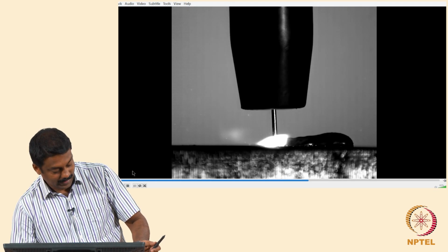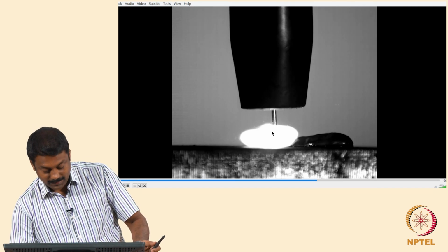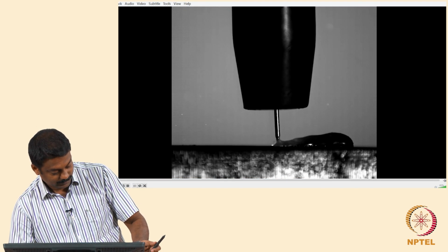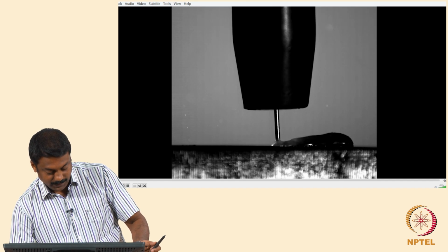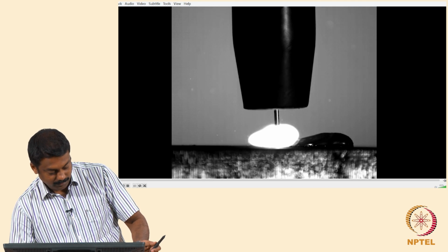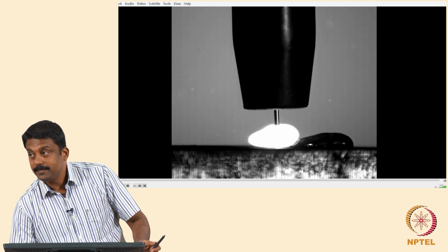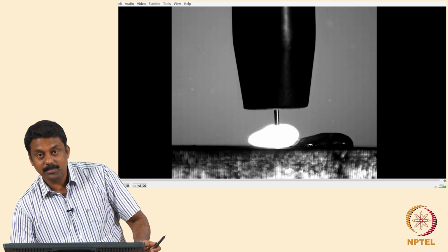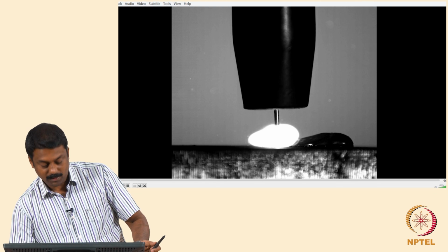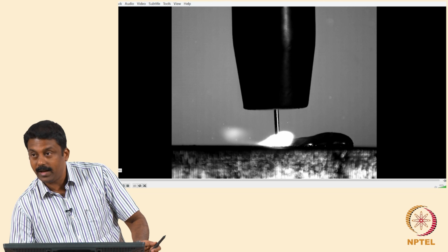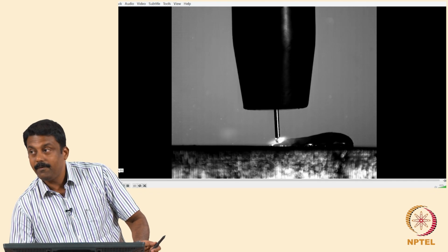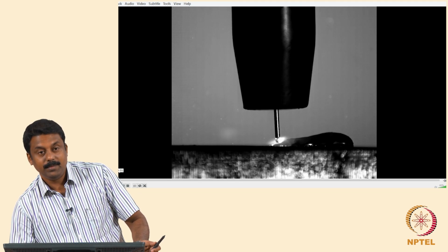So we have this as a cycle. Okay, first the arc is struck. Okay. So this is the first event, the video is recorded. Yeah, so now a pulse. Okay, the droplet is molten. The tip formed a droplet, and then you are also pushing the wire because your feed rate is higher than the melting rate.